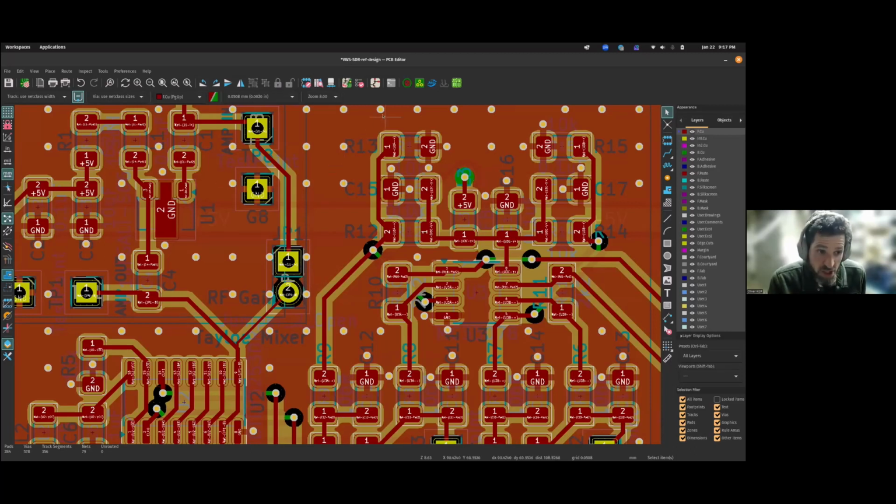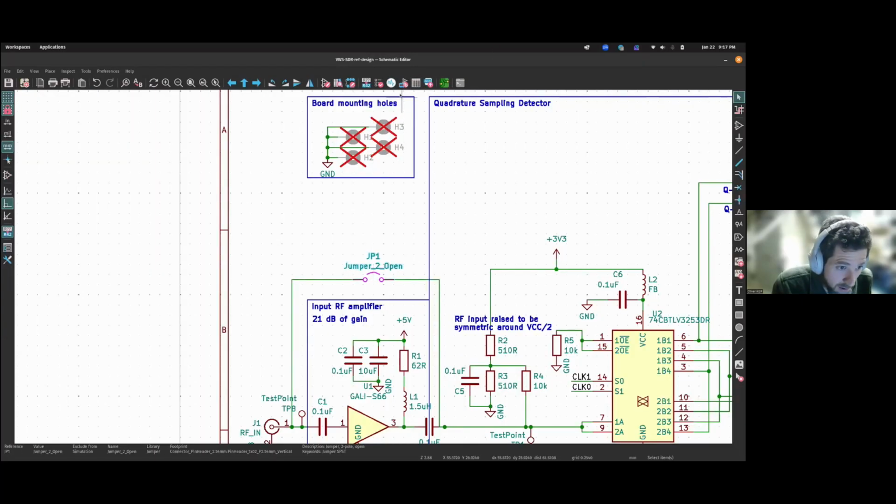It is also possible to go in the opposite direction, though I don't recommend doing this, and I try to avoid it at all costs, by deleting a component on the PCB. And then when I switch to the schematic, there is somewhere here, I can't find it right now, an update schematic from PCB option as well. So you can bring some of those changes from the PCB back to the schematic. I don't like doing that. I recommend that you don't do it. You lose track. I like everything to flow from the schematic and flow through to the end.